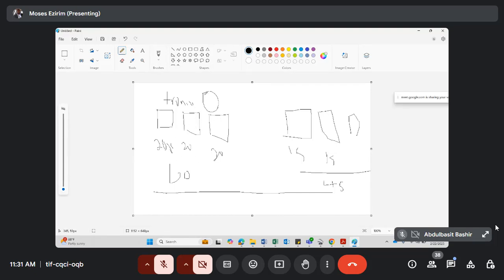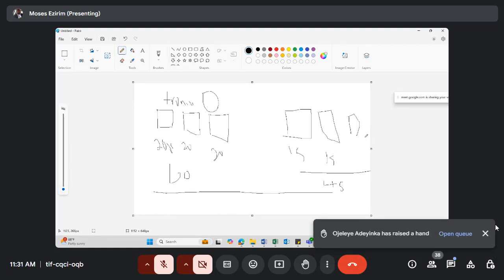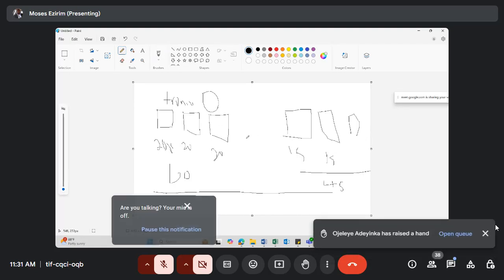So during the day, I should be using it, not getting a zero. All right. So at the end of everything, I'm using from the battery. And once the battery gets to 20% SOC, depending on whatever you set, it calls the generator to come up, and I'm using fuel. And if there is grid availability, I'm using grid, which I'm paying for. So why not just do a correct installation, and at the end, you are enjoying the energy from it.